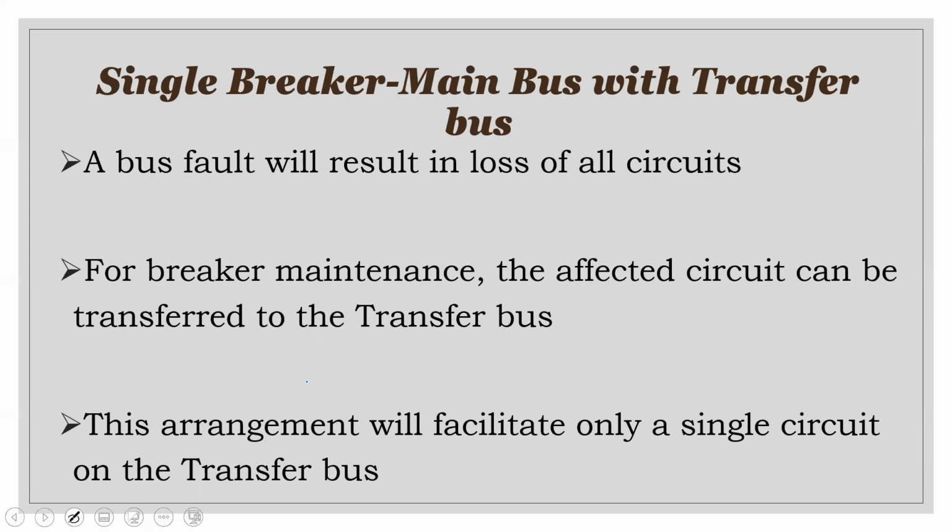And if we go back to what I said earlier in terms of considerations, the bus arrangement is used to facilitate: 1, the number of circuits; 2, maintenance; and 3, we consider the fault implications. And then what we use will be based on the service requirements and, of course, cost.